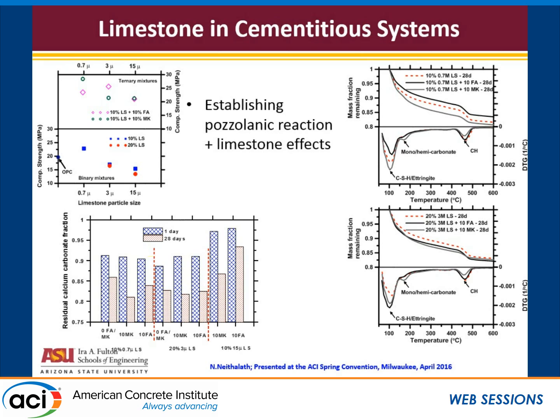Now you're showing that your limestone that you're putting in is not just a filler. It did not have the potential to act as a reactive material if you put it alone. Now you're tailoring the chemistry, you're forcing it to react, and mono and hemicarbonates are not bad things in concrete. It doesn't do anything, it just fills the pores. These are actually denser products than the calcium hydroxide that it replaces. Your concrete is actually going to get stronger and much more durable.